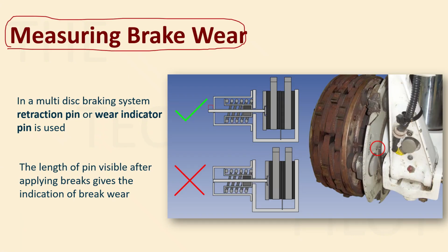All right. So this brake material that you're seeing here, this thing was your stator. So this stator keeps on getting damaged with time, right? With all of your flights, this will get damaged, right? There will be damage because the stator and the rotors are coming in contact, which is creating friction, which is creating heat.